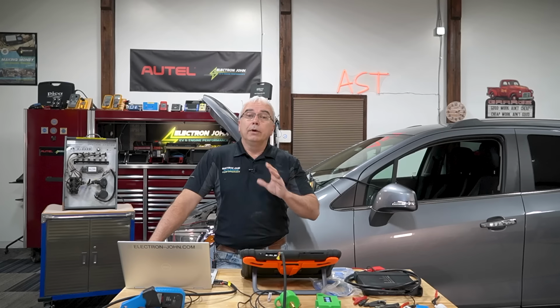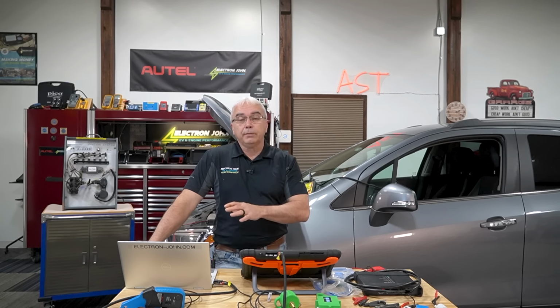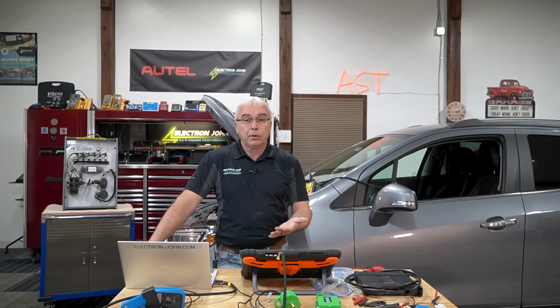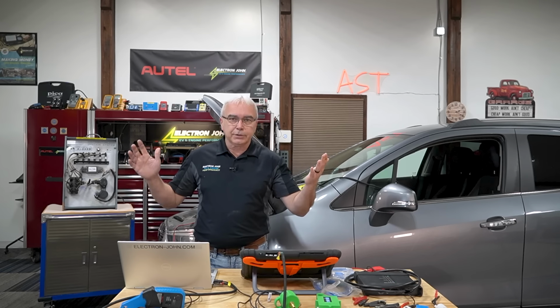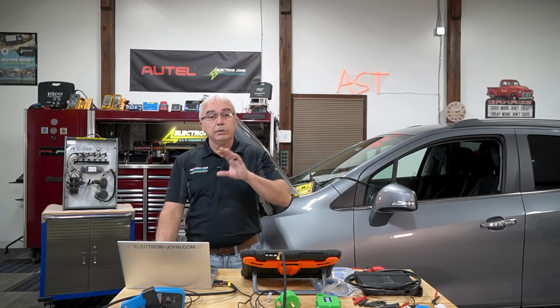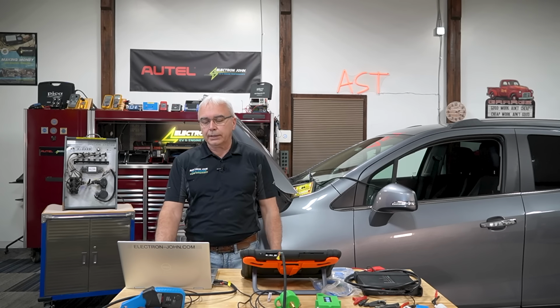If there is a lag, usually it's going to be a hesitation type of complaint, stumbling, lack of power, something like that. Well, that's a pretty good indication that there's a problem with the mass airflow, possibly something as simple as a contaminated hot wire on the mass airflow sensor. And then obviously I'm going to be looking at that sensor for any type of possible glitches as well. Again, I'm always going to be backing it up by looking at other lines of data.